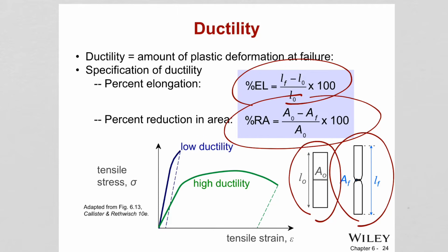You guys need to understand what I can ask in the exam is I can give you stress strain curves of different materials, and I can tell you to compare them, like which is more ductile, which is more brittle, etc. So when you have low ductility, it's brittle because it immediately fractures after some strain. And some materials have high ductility.